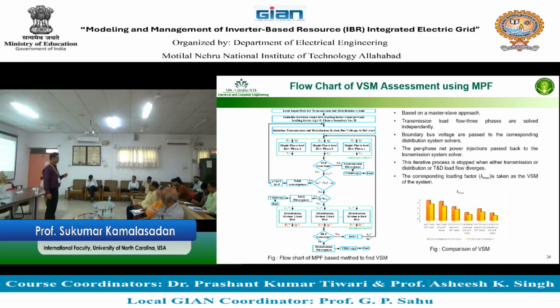It is a study done to see what will happen to the voltage and the electric grid if the PV farms are connected at one point, and whether you need to add any compensators. From what I heard from IISc, in India there are places enforcing adding StatComs, to improve the voltage near the PV farm because of some voltage related problem.